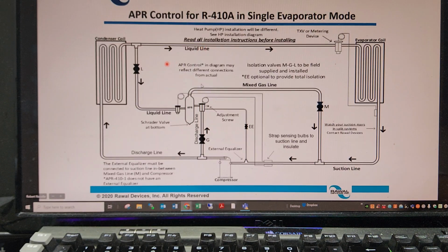Oh, I see. All I got to do is move this liquid injection down, move the T down, and then put my dryer to the left of the T. Got it. We're good. Exactly. Put the dryer and then put the T. Understood. Got it, sir. Perfect. All right, let's move on here.